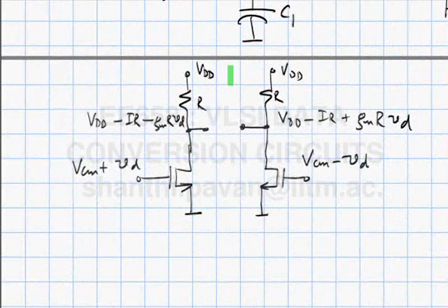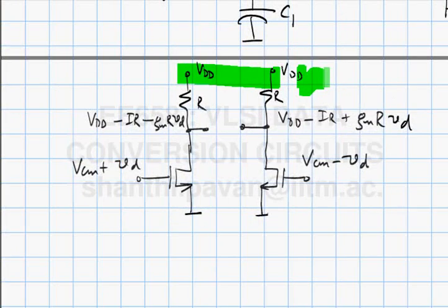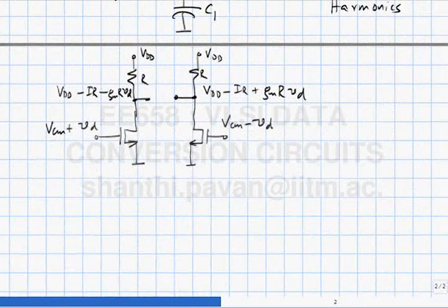A little thought will show you that if I wiggle VDD a little bit, then the gain from VDD to both the outputs is the same. So the transfer function from an incremental source on the supply voltage to the differential output is 0 because of cancellation. And in our earlier classes we have seen that you can in fact do better than this.